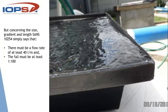So what I hope to achieve today is just to show you what different circumstances look like at 40 liters a minute, in terms of pipe configuration, because that's what I set out to achieve: to see what is able to achieve that discharge rate and what is not. So let's go back to 10254. It says there must be a flow rate of 40 liters a minute and a fall of at least 1 in 100. So how do we achieve this?